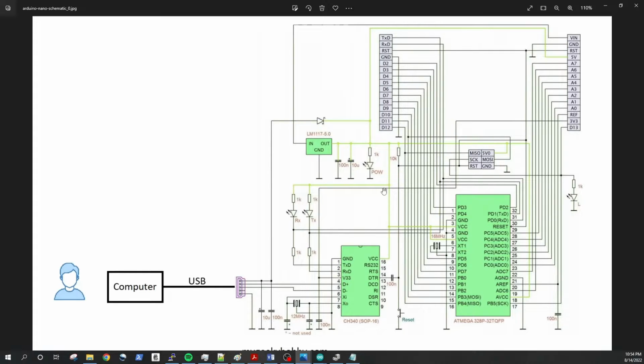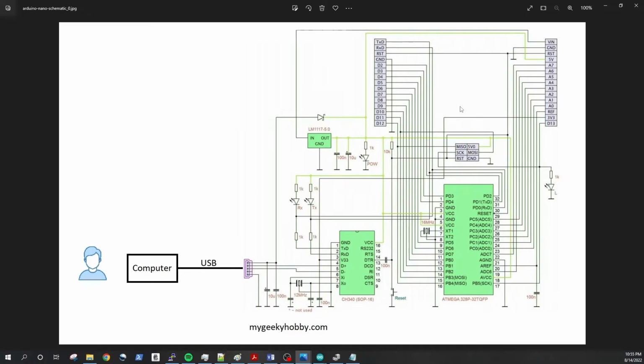So the suspicion in this case is that as the communication is coming out of the microcontroller, out of the 328P, it's supposed to be reaching this CH340 and properly being converted and sent over USB into the computer. Something is likely happening to that signal.